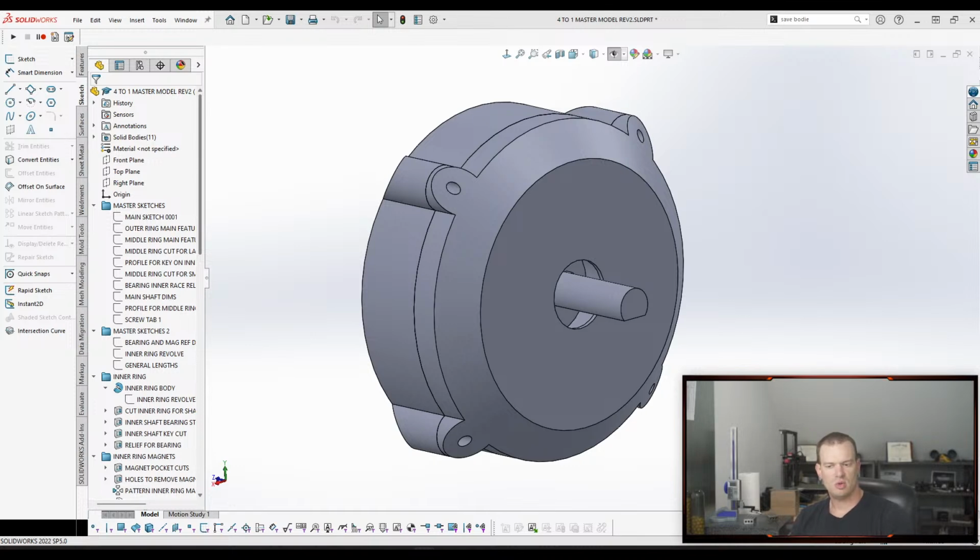You'd only be trying to access the skeleton sketch if you're trying to change something that is a relationship to another part. So I think that having that hard cap on, if this is relationship geometry within a sketch and it can get shared, it goes in the skeleton sketch.